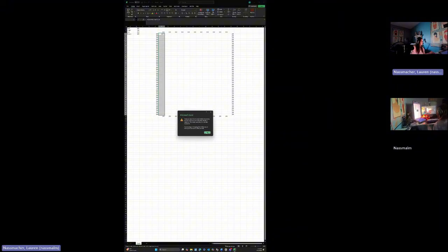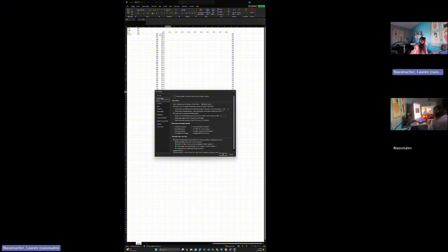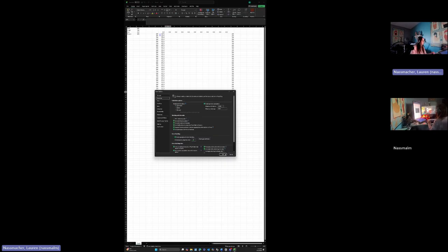you'll find that the Excel spreadsheet does not enjoy this. That's because it's a circular equation. In order to amend this situation, we have to change some settings. So to change that, we're going to do File, go down to Options. It's really far down. Then go to Formulas, Enable Iterative Calculations, increase the maximum iterations just for safekeeping, apply that, and now our equation works.